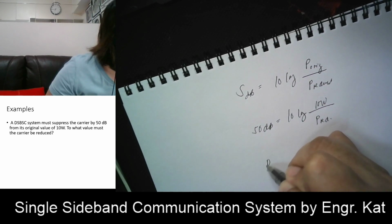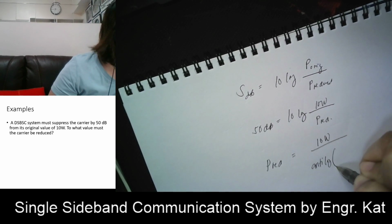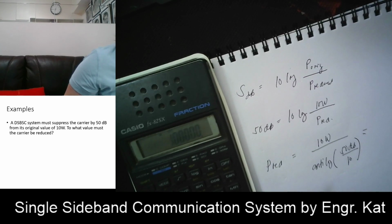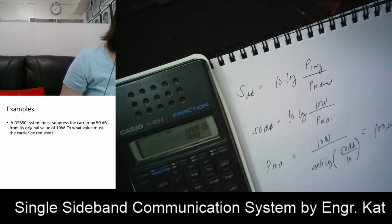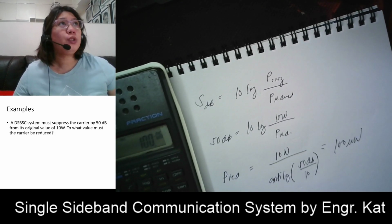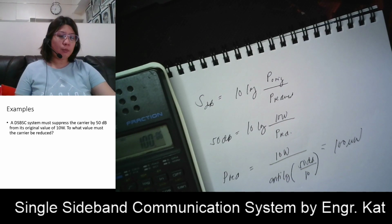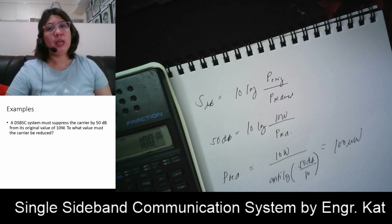Okay, so solving for the reduced value, this is equivalent to 10 watts divided by the anti-logarithm of 50 dB divided by 10. So that will give you what? 100 microwatts. So from the original 10 watts, you have to reduce that to 100 microwatts so that you can have a suppressed carrier equivalent to 50 dB. Okay, so those are the types of problems that you might encounter when talking about single sideband communication.